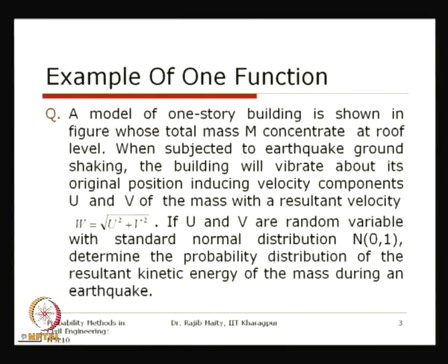So we will take a simplified structure. In the idealized case, the general way of analyzing earthquake force is to assume a concentrated mass at the floor level, obtain the force at that level, and calculate the kinetic energy. So here we will take one such problem for an idealized one story structure.